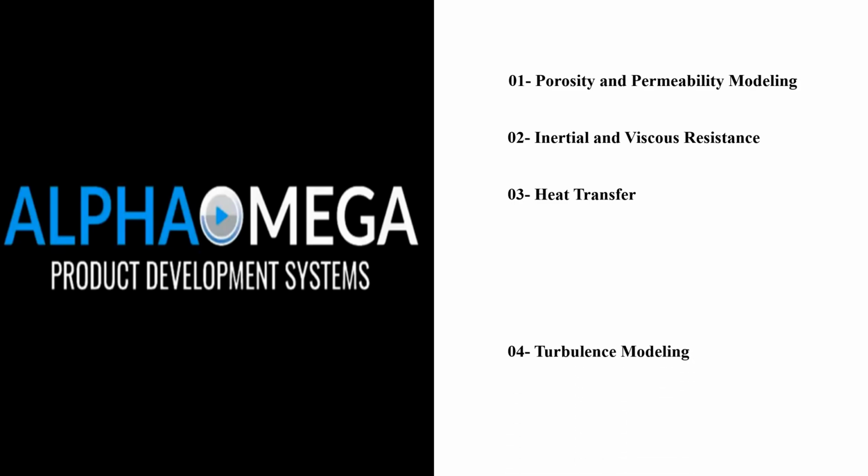Turbulence modeling. The software is capable of modeling turbulence in porous media. Turbulence is the chaotic movement of the fluid, and it significantly affects the flow and heat transfer in the porous medium. ANSYS Fluent uses various turbulence models such as the k-epsilon and k-omega models to simulate turbulence.